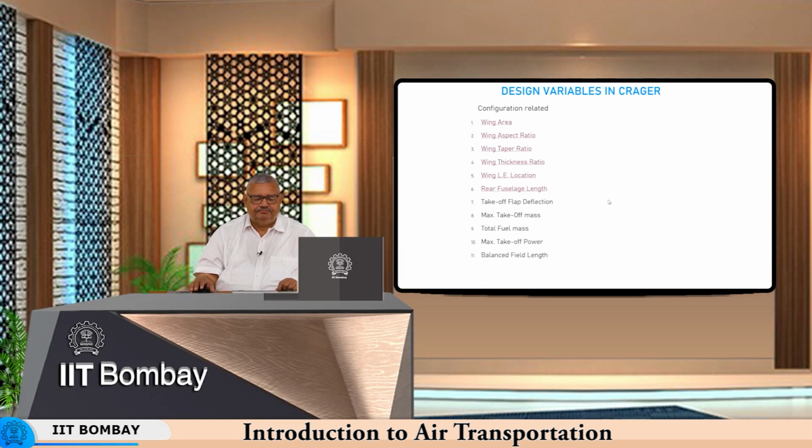Coming now to the trajectory or the profile related parameters, there are, as you know, 9 of them. The first one is the climb throttle. As I mentioned in the preamble, commuter and regional aircraft are a very interesting subcategory of transport aircraft, where not only what you fly, but how you fly is important. This is one of the hows. At what engine setting do you climb? Do you have a very steep or sharp climb, or do you have a very shallow or low angle of climb? This depends on how much throttle is being provided during the climb phase of the aircraft.